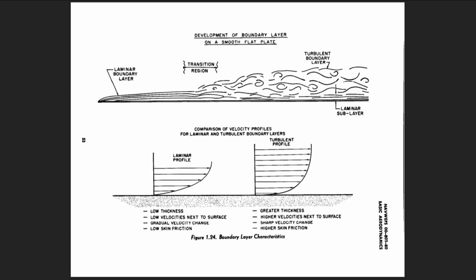The turbulence which exists in the turbulent boundary layer allows determination of the point of transition by several means. Since the turbulent boundary layer transfers heat more easily than the laminar layer, frost, water, and oil films will be removed more rapidly from the area aft of the transition point. Also, a small probe may be attached to a stethoscope and positioned at various points along a surface. When the probe is in the laminar area, a low hiss will be heard. When the probe is in the turbulent area, a sharp crackling will be audible.